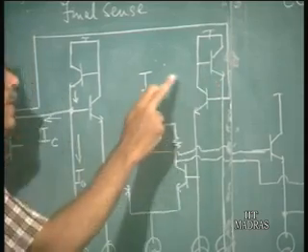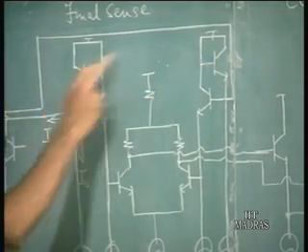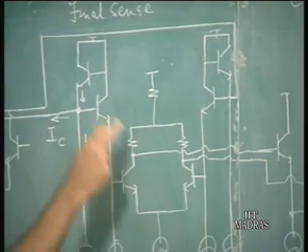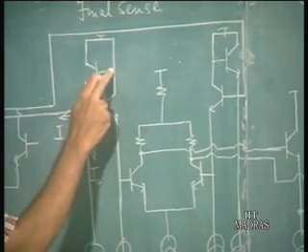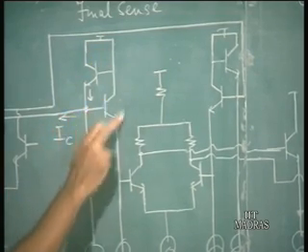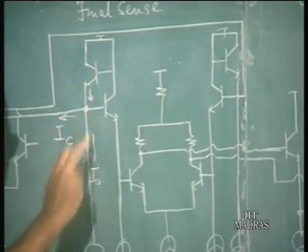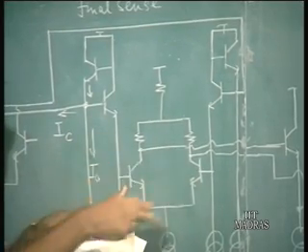Okay. So, there is going to be a difference in the base emitter voltages of these two transistors, and that is what is sensed. So, what you have is this VBE difference. This is VCC, say VCC minus VB, and then you have an emitter follower. This is nothing but an emitter follower, which is again fed to the base of this differential amplifier.